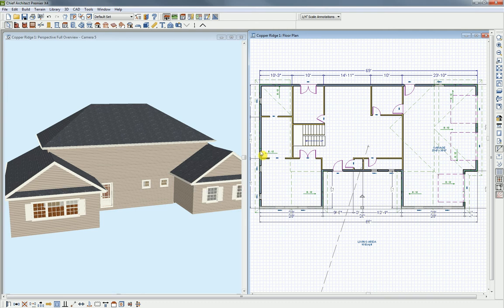Now, in addition, I'd like to run a gable that comes from across this wall as well as here. So when I select on this wall, it's giving me a selection of this entire wall. So in this case, I'd like to break that wall so I can run my gable just across here. So there's a handy tool called a break wall tool. It snaps right to that intersection. And now, when I select this wall, it gives me that selected roof.